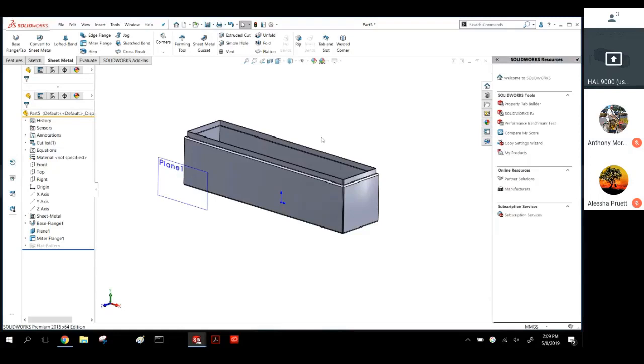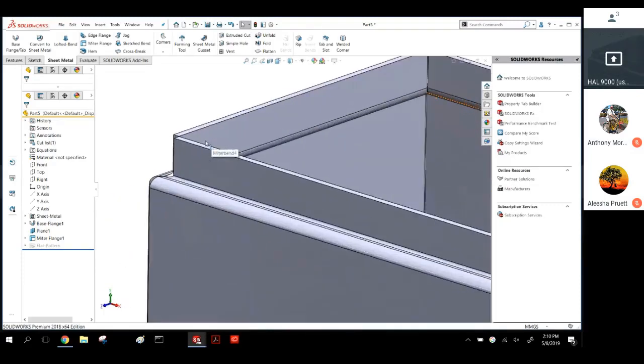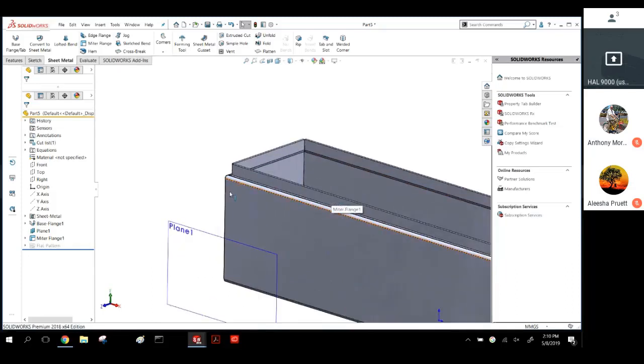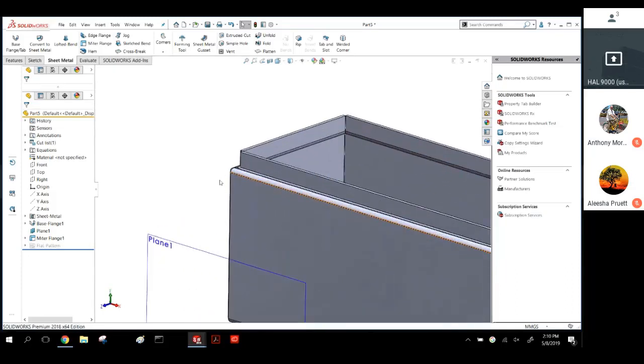I'm going to do it as a multi-body part. I covered in weldments doing multi-body parts. Just like that cardboard part that I had individual bodies. You can shoot the individual bodies out if you need them to be tracked as their own parts. If you want to have individual part numbers for the parts and that sort of thing, a lot of times we'll do that. But it's a good idea to build it as a multi-body part when you're doing things like boxes with lids, so your lid is always going to fit. There's never going to be a time that you have a lid that doesn't fit your box because the lid is actually defined by the box.